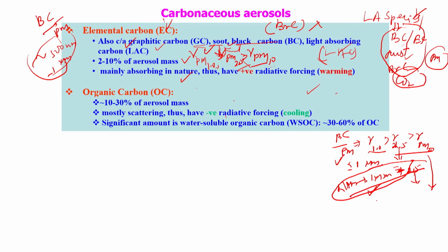So, if I just talk about the ratio of black carbon in 2.5 to 10, it is somewhere around 0.8 to 0.9. So, this is very high ratios. So, almost all the carbon is contained in the PM2.5, very little is there in the 2.5 micrometer or higher. Okay. So, this is usually asked to confuse you, that why the black carbon percentage contribution is lower in PM10. So, you have to give the logic very clearly, otherwise it will be very difficult.